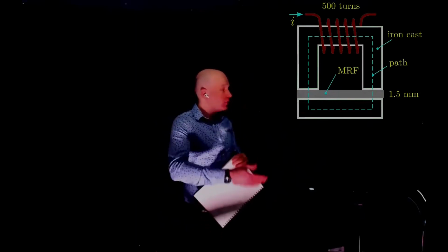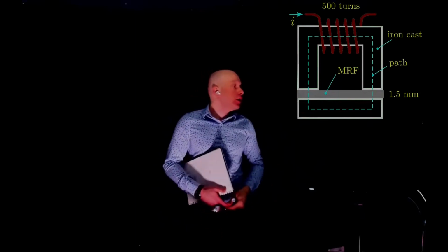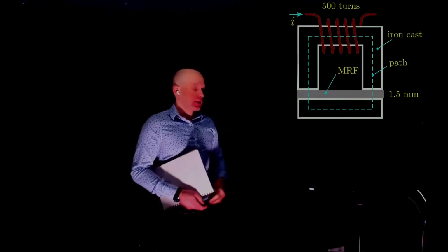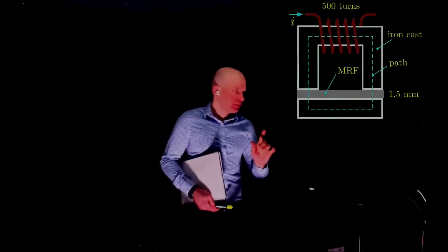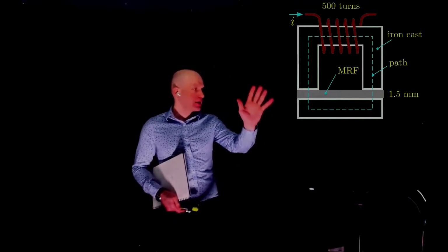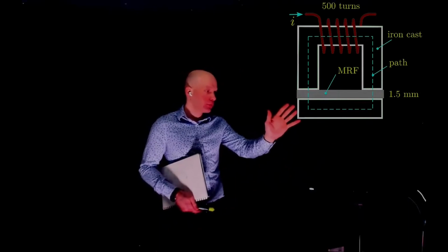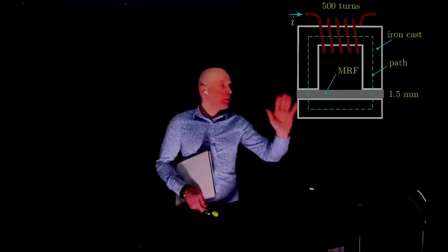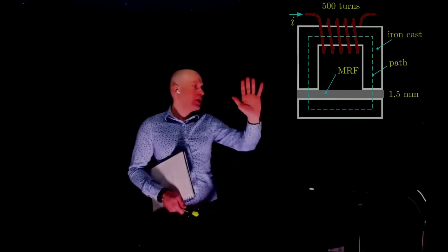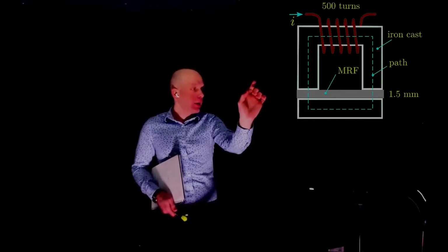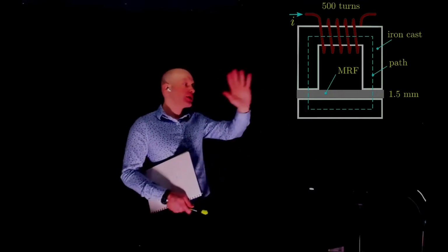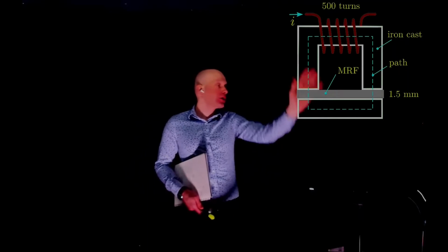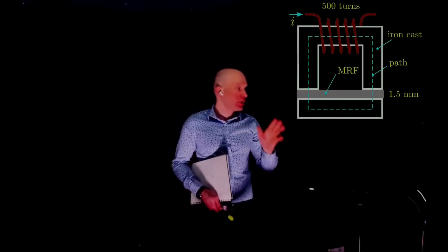We know the relative permeability of these materials, and you want to establish 0.8 Tesla. Now there is a key concept here. Notice that this thing has the same cross-sectional area. It's not said on the paper, but it goes into the lightboard to a depth that is constant, which means that the cross-sectional area throughout this entire thing is constant, is the same.